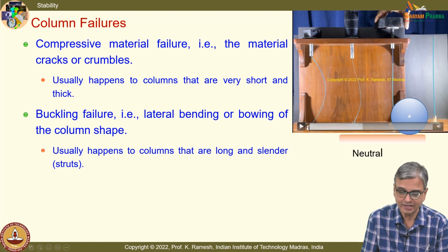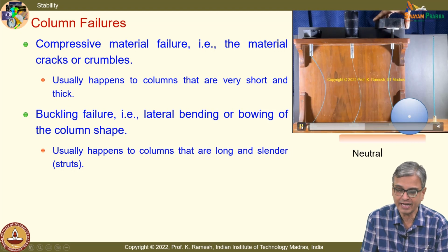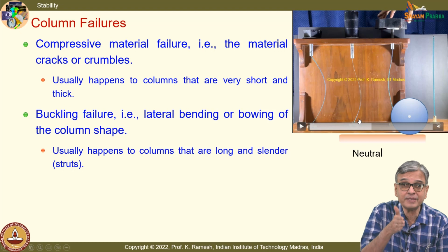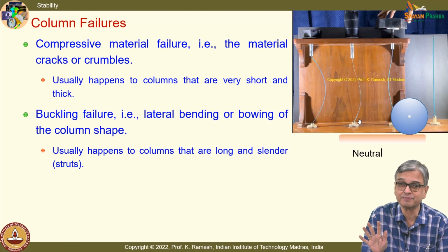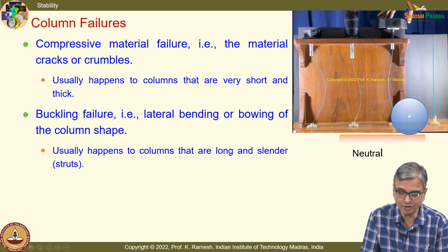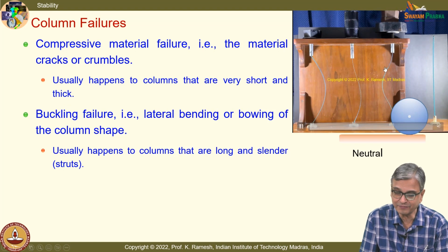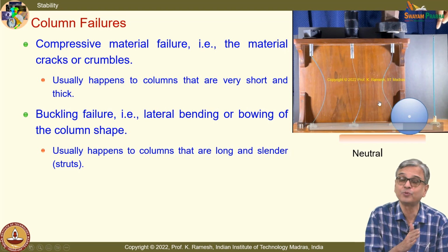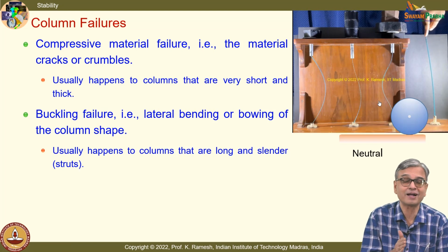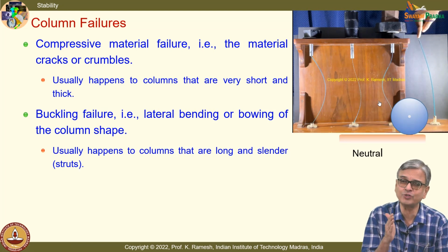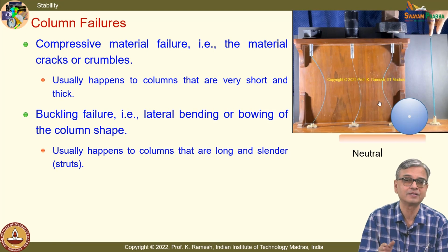And look at the fixed end. You could see that beautifully. I have this load, I have the deflection. So, the system is in equilibrium, not with the column being straight, but in a deflected shape. Suppose I increase the load further, you could see that it has taken another shape, and I increase it further, it takes another shape. So, it beautifully illustrates the buckling phenomena. What you see is actually neutral equilibrium.